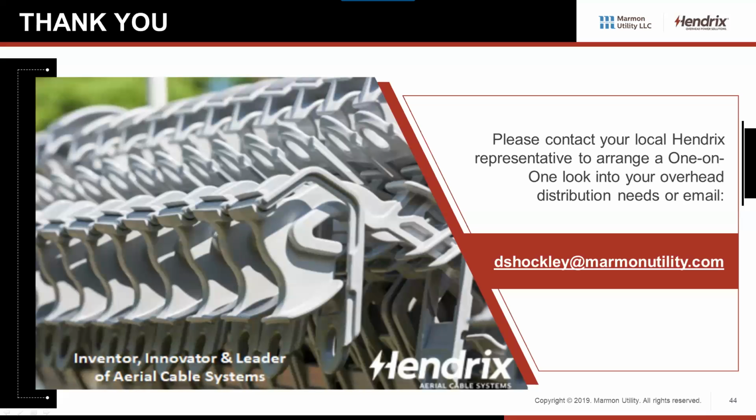But again, the incidence of that is so small because of the environment where spacer cable tends to be used. If you notice some of the pictures where you get into steep slopes or mountain type installations, or out in the desert for renewable installations, solar farms, wide open spaces, and then you've got ductile iron poles or steel poles, that's where it becomes imperative that it's properly grounded and the resistance is kept relatively low.